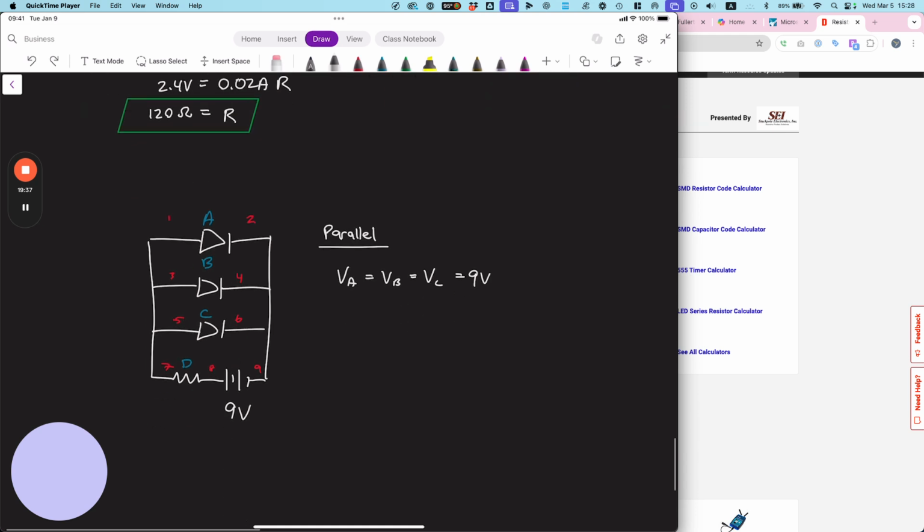I'm thinking... There is not 9 volt, there is a 2.2. What is? The VA, VB, VC. Yeah. Should I put the resistor here, John? What do you think? Instead of at the beginning? Because right now it's basically just having a lower voltage by having the resistors in series. Yep, you can do that. I don't see a point in having this resistor since it's just in the beginning. It's like, you might as well put an 8-volt battery instead of a 9-volt battery, right?